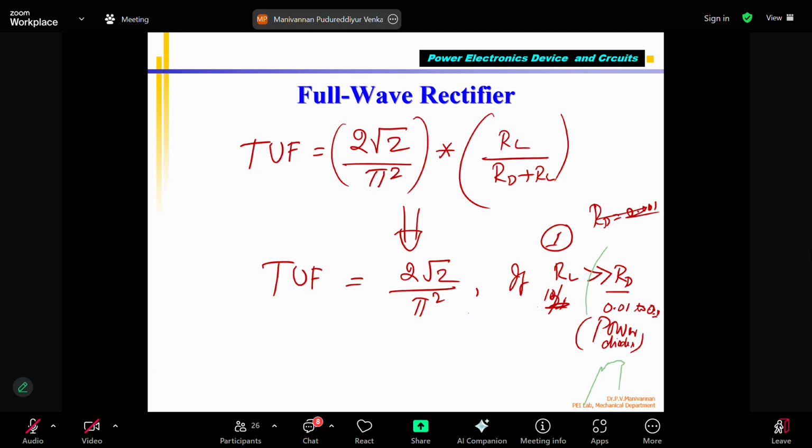I stop here. In the exam, you can expect a rectifier circuit to be drawn, and the input voltage is supplied. Transformer is given. Transformer ratio is given. Transformer input voltage 220 volts. Step down transformer ratio is 25. Then we get VS, the secondary voltage, equal to 220 divided by 25. 220 divided by the transformer ratio will be the secondary voltage.